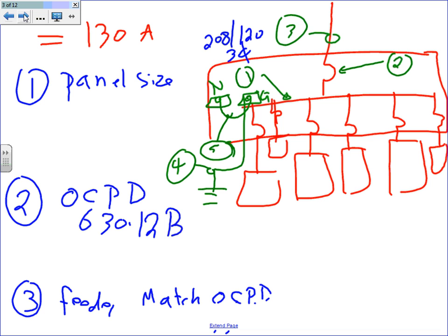If they were single-phase welders, you would do the same calculation for single-phase welders. You really go by the amps. By the way, they all have to be either 3-phase or single-phase. For all practical reasons, on 30 amps, this could be 240/120 single-phase, and the panel would be single-phase then. The welders that we bought are all 3-phase 208/120. Okay, cool. That has to be given.